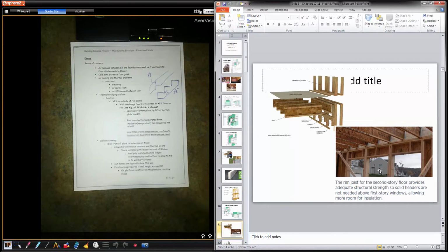This scenario down here is basically, we went to a passive home 2 years ago, and it was done this way. So the walls are platform framed. Notice no lintels over the windows. So if you have lots of windows facing south, for example, as opposed to having a lintel above every single window, what you could do is put the lintels up in the floor system.